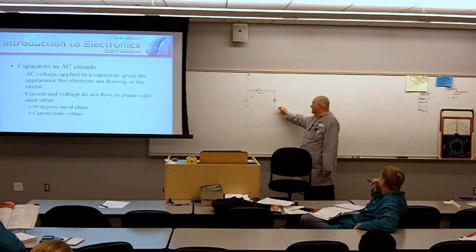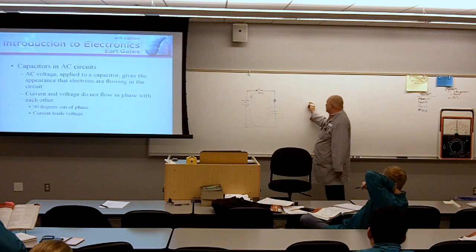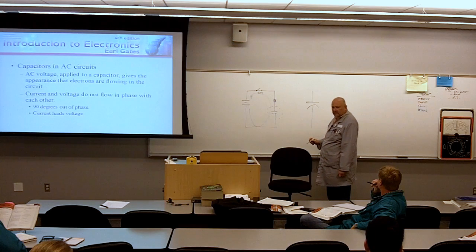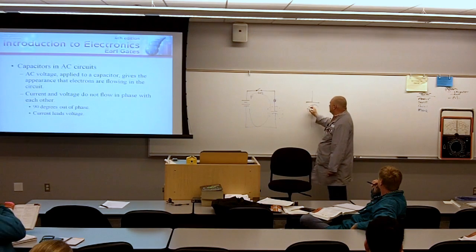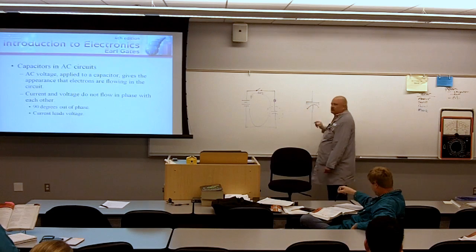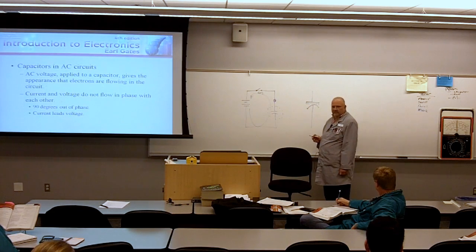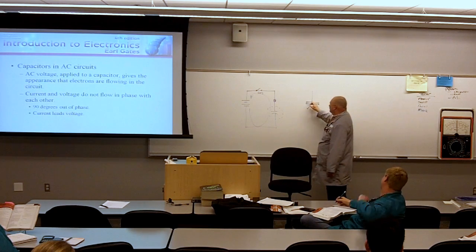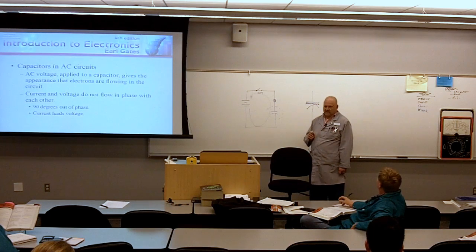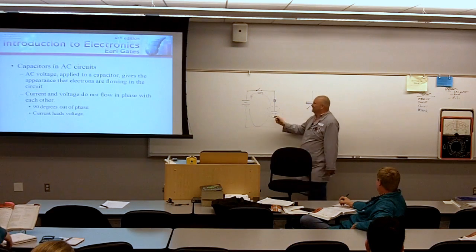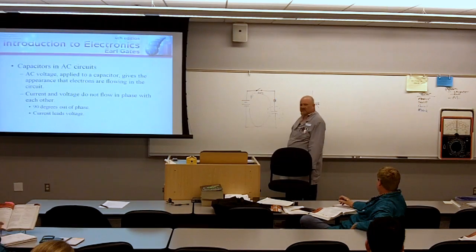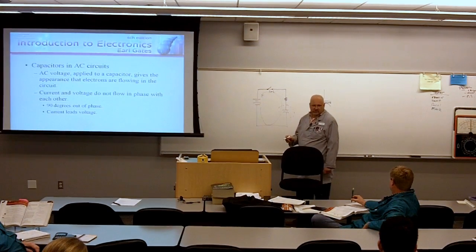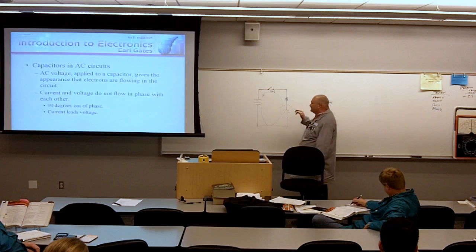Let's take a closer look at what's going on right here, okay? This component here is a capacitor. What is a capacitor? Two plates separated by a dielectric material. It's like a battery, but this is a dielectric material. A dielectric material is a fancy way of saying insulator. So let's go back to the circuit here. When I close the switch, does current flow through an insulator? So Mr. Carter was accurate when he said the capacitor begins to charge, right? Let's talk more about that charging.